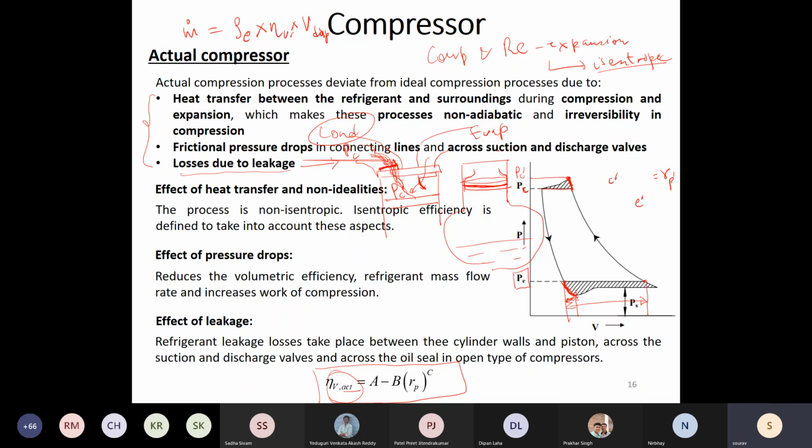So that's why there is a third category of compressor. One is completely sealed, where in order to do maintenance, you will have to cut open the compressor casing, which houses the motor also. The other one is the open type compressor, where all these valve plates, everything is accessible. We have a third category, which is in between the sealed and the open type, called the semi-hermetic type, where only the cylinder head, and hence the valve plate, access would be given.